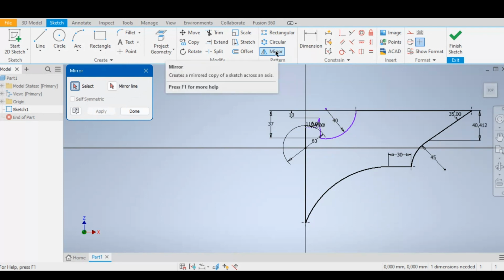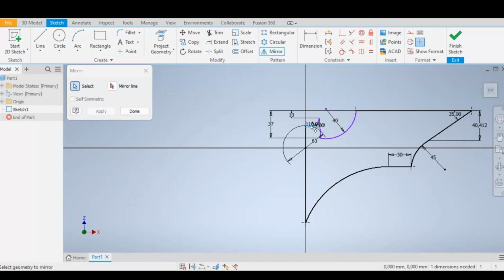I'm going to select the curves that I want to mirror across my center line. So then I'm just simply going to select all of our curves from this. As I said, you can then refine these dimensions to something that you would like. But from here, we're going to select all of our curves, and we are going to exclude our center line when you're selecting your curves.